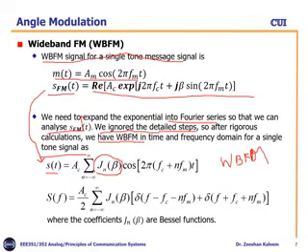So from here we can notice that for different betas we have different Bessel values, or Bessel functions, for varying n. These coefficients are similar to the previous coefficients which we used in the narrowband FM. What was that? That was the amplitude of that narrowband FM wave.